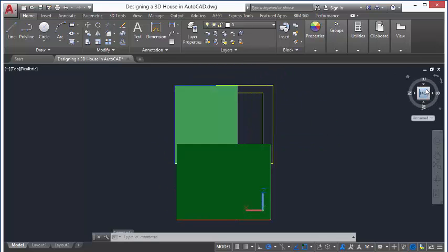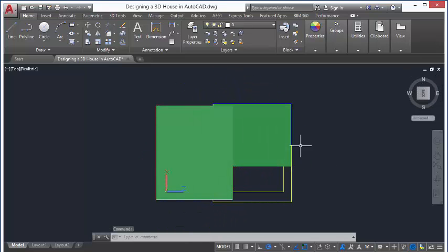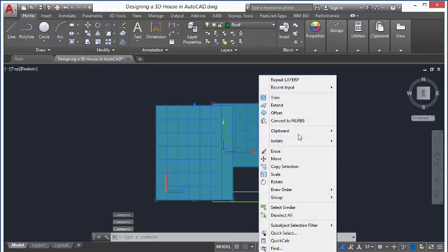Go to the top view. Use this arrow. When you select the top view, sometimes the model is not oriented to the position where you want it to be, but that will not be a problem. Use this arrow to spin, rotate around the model. Select the 2 roofs, right click, Isolate, Hide Objects.